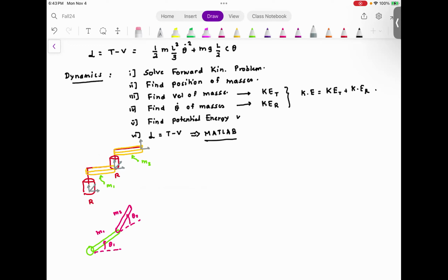You assign the coordinate systems, find out 0h1, find out 1h2, and at the end you can find out 0h2, which is 0h1 multiplied by 1h2. And let me quickly write these matrices.